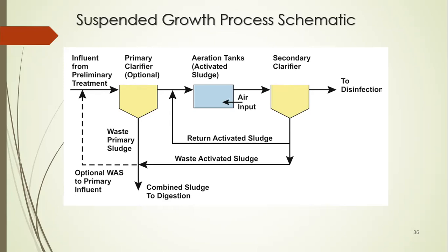You have to maintain a favorable pH in this system. So once the water spends certain time, typically 4 to 24 hours in the aeration tank, the whole liquid will move into the secondary clarifier.